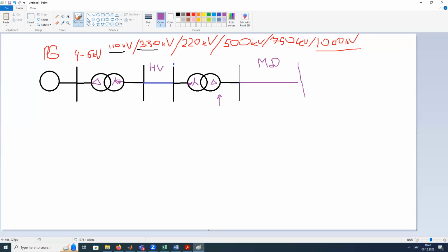Faults are not dangerous for the network. There could be thousands of faults in this distribution network, and it could still operate, but relay protection or people should deal with this because it is dangerous for people. In this case, we are interested in protection of our transmission line over high voltage devices. That's why we use this type of star connection with a very high short-circuit current. Here we use a different philosophy and a different connection.